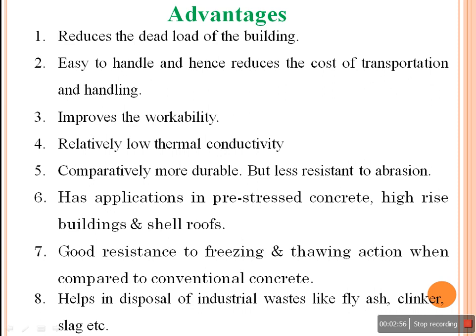So what are the advantages of lightweight concrete? First one is it reduces the dead load. When you're designing any RCC member, the first load we take is dead load, that is the self-weight of the member. It gets very much reduced. Because the dead load of the concrete is less, it is easy to handle, and hence it reduces the cost of transportation and handling.